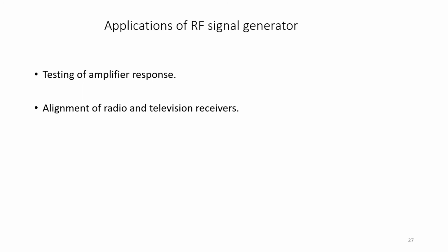So 2 or 3 tank circuits may be connected through the same line, so that when you change or adjust any one stage frequency, all the other stages' frequency must be changed in a similar manner. So that is the alignment. Alignment must be correct, or else the output will be distorted.